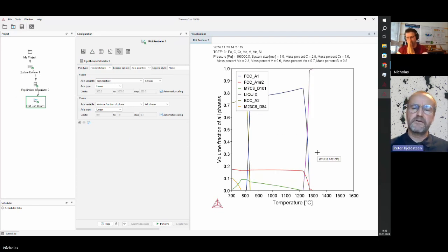Then we went back and said, okay, we are protecting the steel with a nitrogen atmosphere. Maybe nitrogen is an activator or an elongator of this arm of the liquid, so it's not only 20 degrees, maybe it's because it solidifies at temperatures around 1500. That was a bit difficult to understand. So can you add that this is in an atmosphere of nitrogen, and then see what happens, an equilibrium with a melting phase and a gas phase of nitrogen?